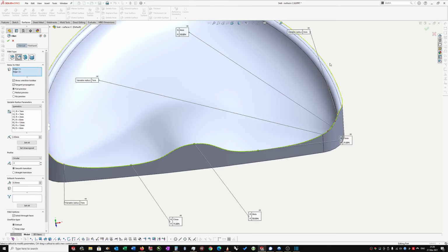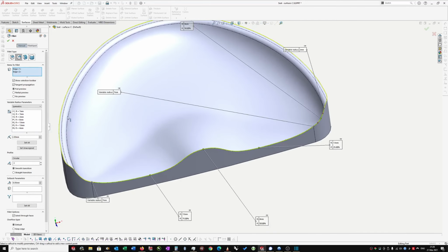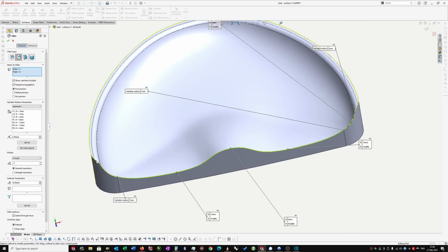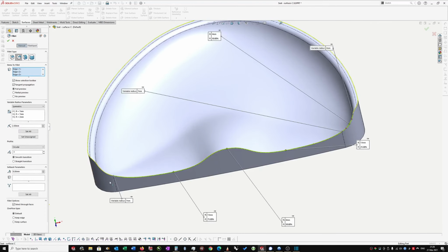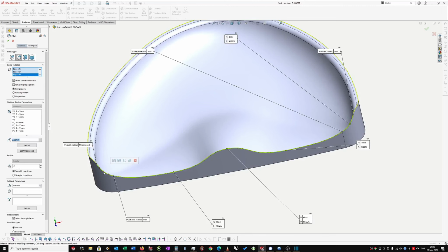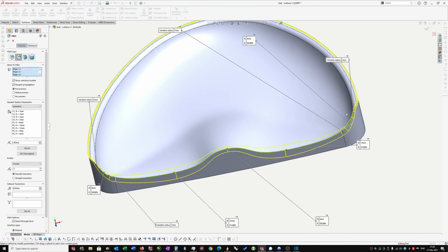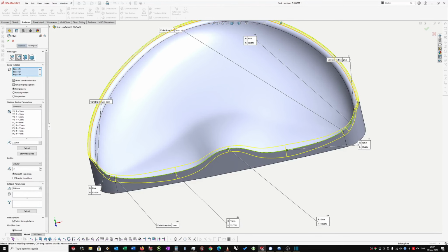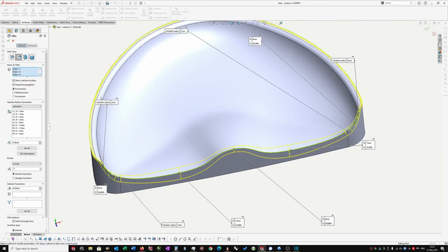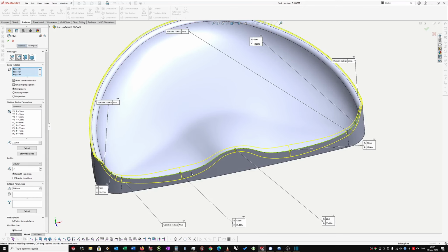Okay, it's gone a bit quiet. Why is that? Well, let's see. Let's move on to this other edge and see if we can get something similar going. So, middle one, I'm going to double click, say 4. Edge 1, 2. So okay, that's the reason why this one here suddenly couldn't have a preview, is because it had picked up that this dimension here, 7, was going to go all the way around, and that was going to be a problem across this little edge here.